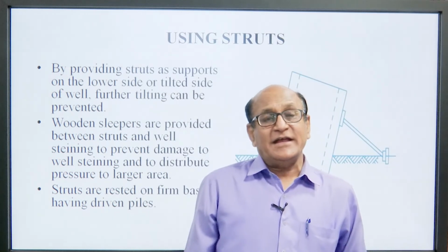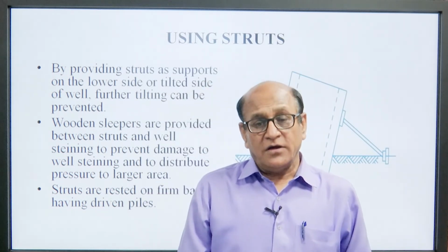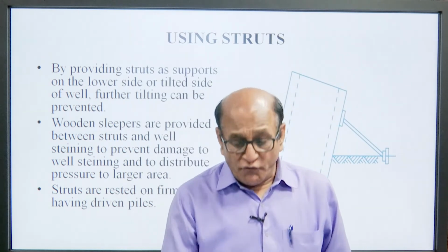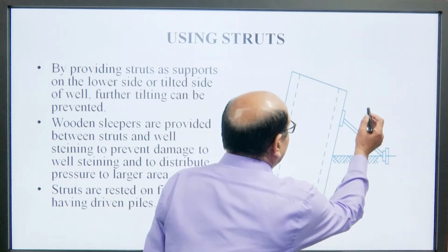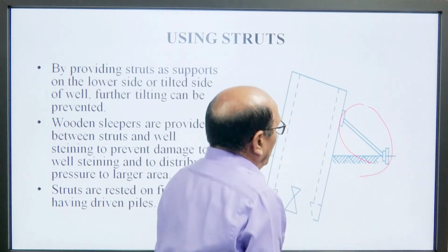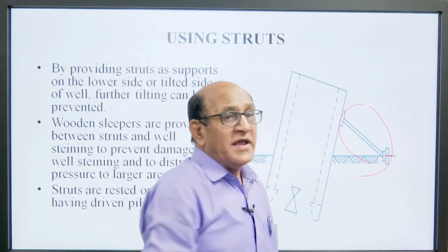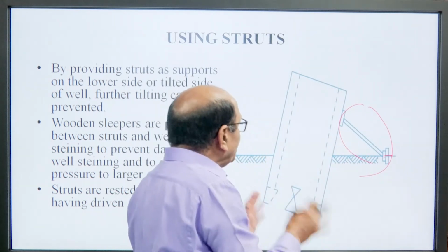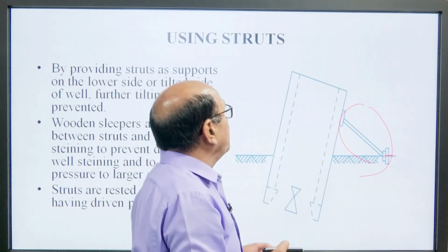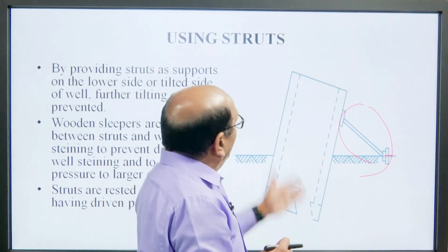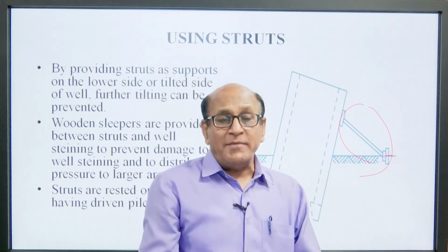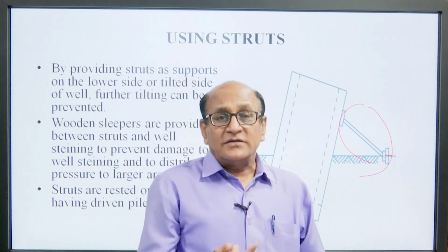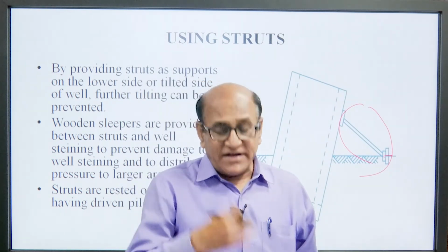Using struts: if our well is tilted, we can provide struts, where the lower edge should be firmly fixed on the ground. So, the tilting of the well will stop immediately, and then we can make a provision to make the well vertical.